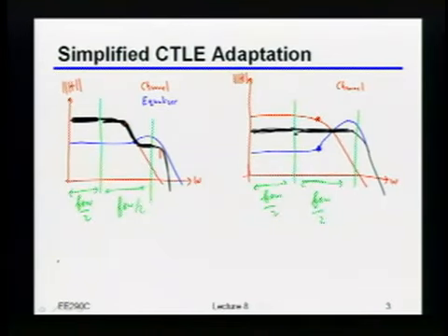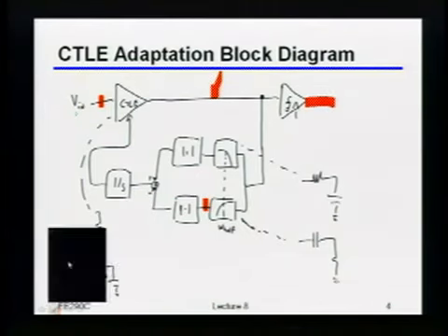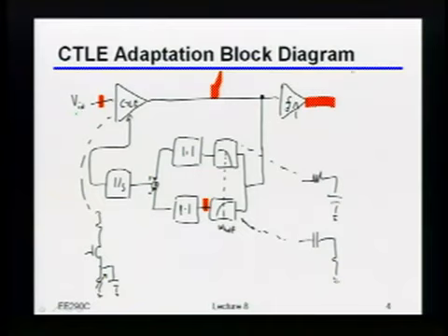What about doing this in the digital domain after the? Okay. There are versions which will turn out to do something similar, but remember, I've only got a single bit coming out of here. If I actually see spectral differences in the bits coming out of here, that either means my data is bad because I'm not sending white data, or it means I'm actually making mistakes.